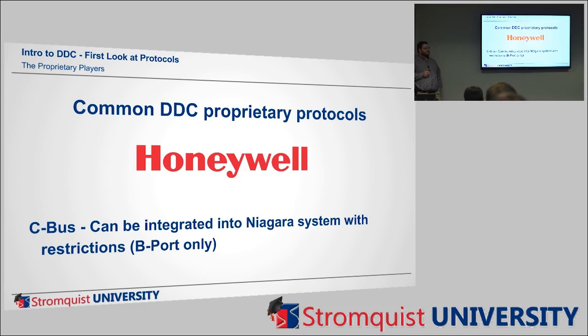And it even gets down to there's different levels of open on BACnet or LON. Because those are open protocols, manufacturers can say, you know, we talked about those SNVs, those standard network variable types on LON. There's actually custom ones that a contractor can write to. But the problem with that is if I have a custom type of point on my BACnet or LON device, the only thing that can see that custom type of point is my other controllers that are programmed with that same custom type of point. So they all play games to try to say, yeah, we're open, but how open are you?